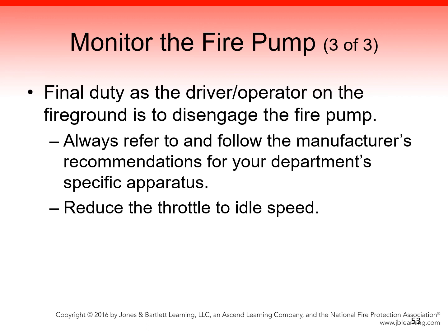Your final duty as driver-operator on the fireground is to disengage the fire pump. Follow the steps in Skill Drill 11-6 to disengage the fire pump with an automatic transmission. Always refer to and follow the manufacturer's recommendations for your department-specific apparatus. Reduce the throttle to idle speed.